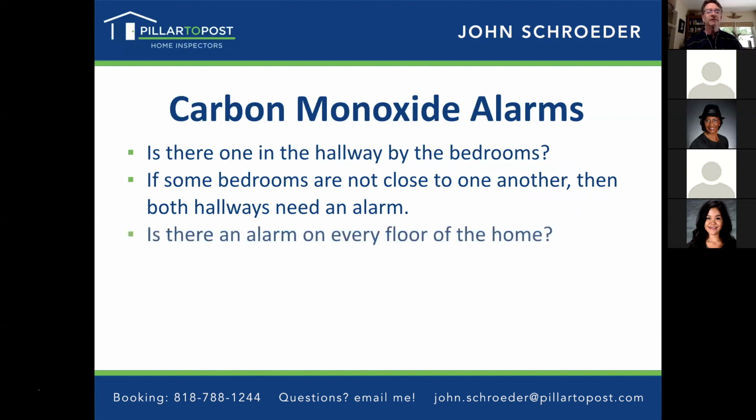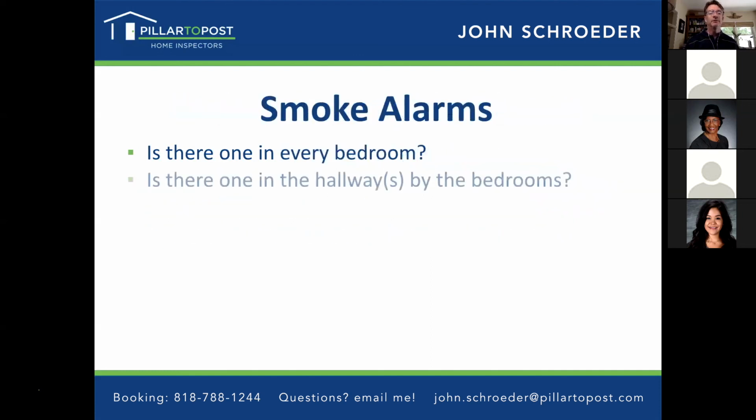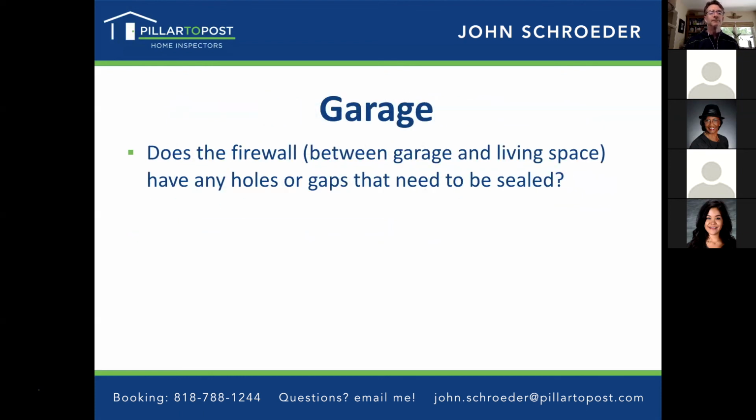But you want to have carbon monoxide alarms on all levels of the home and outside all sleeping areas. Smoke alarms in every bedroom and outside of sleeping areas. The garage needs to have a firewall that doesn't have any breaks or gaps in it between the home and the garage.